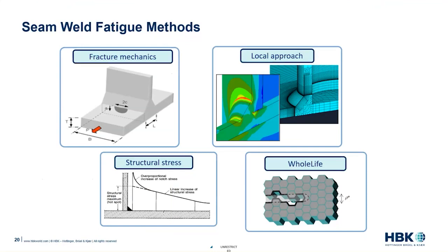And this works from a stress which is in essence the maximum stress at the toe or the root of the weld, but excludes the effect of the stress concentration, this KT factor, where this, together with other effects introduced by the weld, are effectively included within the stress life curve for the weld itself. And it's this approach that we're going to concentrate on.